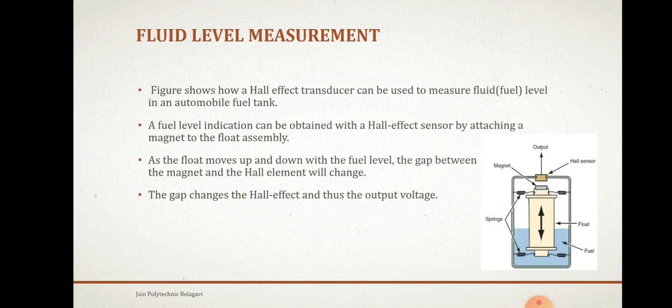The next one, fluid level measurement. Here we are measuring the fluid level. The figure shows that the Hall effect transducer can be used to measure fluid level in an automobile fuel tank. A fuel level indication can be obtained with a Hall effect sensor by attaching a magnet to the float assembly.